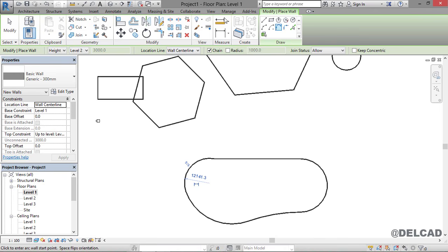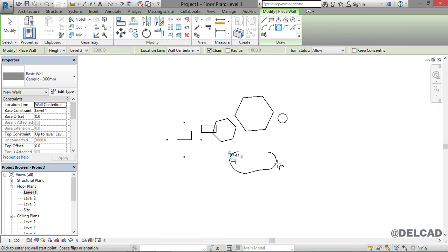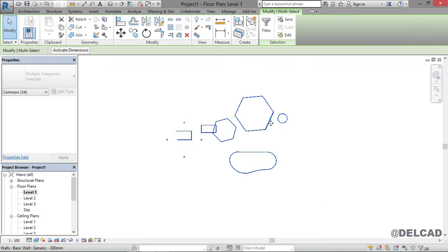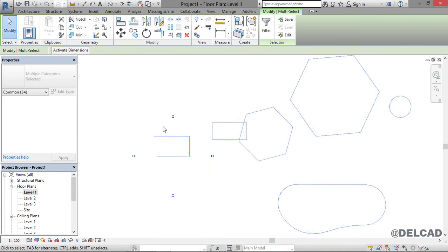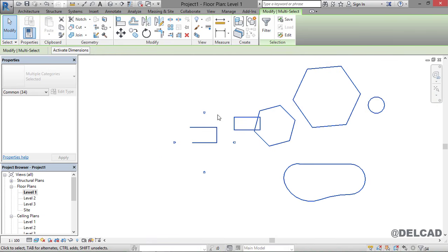here under the ribbon. So now that we understand how to carry out different drawings of the wall with this draw panel, let's see how we can create a simple building with this wall tool. We're going to go ahead, click and drag to select all of these walls which we created and delete them. However, we can see that our elevation tag is also selected, so in the course of deleting this, we are going to delete the tags as well.